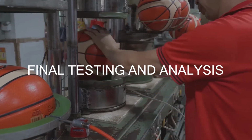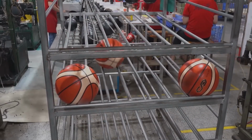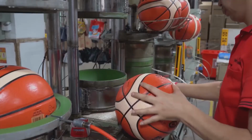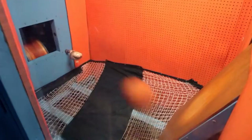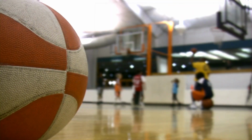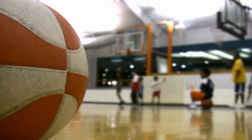Phase 4. Final testing and analysis. The final phase ensures the basketball meets all necessary standards and is ready for commercial use. Bounce test. The ball is dropped from a height of 72 inches. It must bounce back to a height between 52 and 56 inches to pass. This test ensures the ball has the proper elasticity and air pressure.